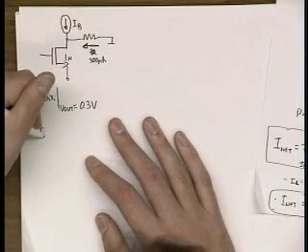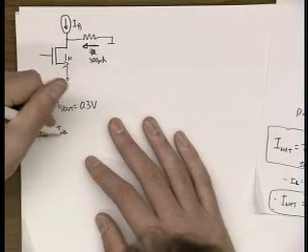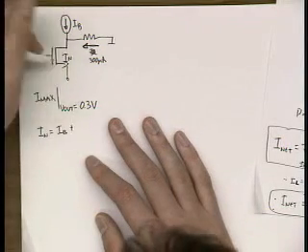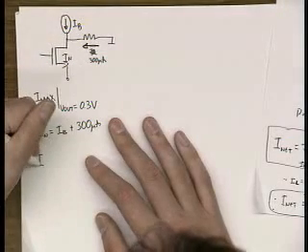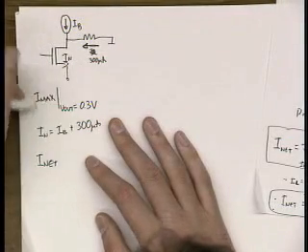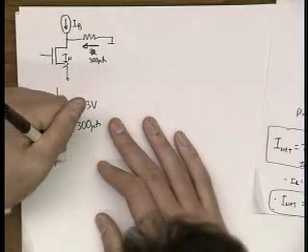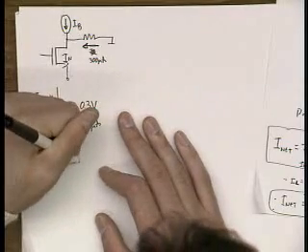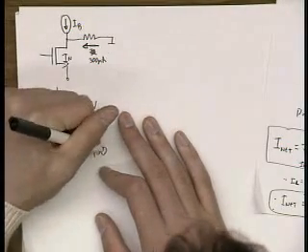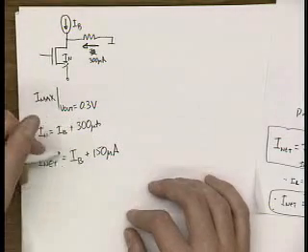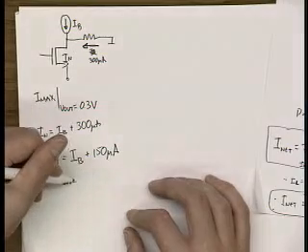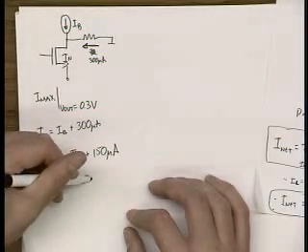So IN is equal to IB plus 300 microamps. So I net is IB plus IN over 2, so it's equal to IB plus 150 microamps, okay? When V out equals 300 millivolts.